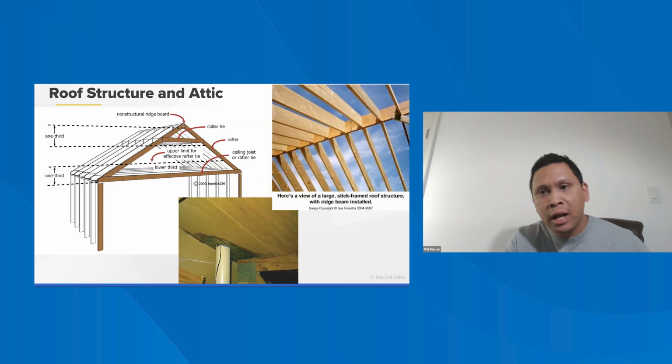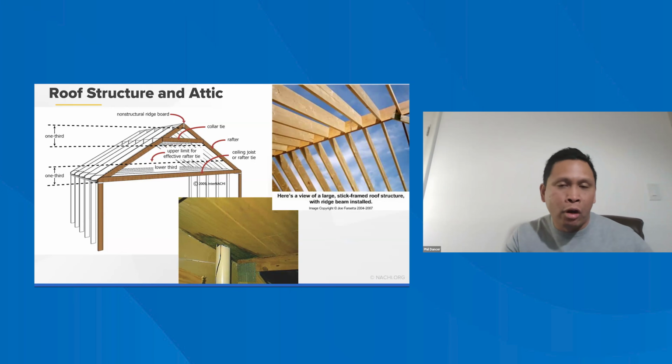I typically don't see truss uplift all that often, just because the builder is trying to do a really good job at controlling the temperature differences for the home itself. They're trying to insulate the home, so they're putting insulation into the attic, and also into the walls. They're also using that spray foam that we talked about earlier, called fire block, to try to prevent airflow from traveling from one floor to the next floor, which would create that temperature difference.